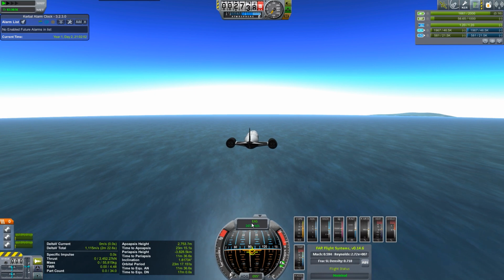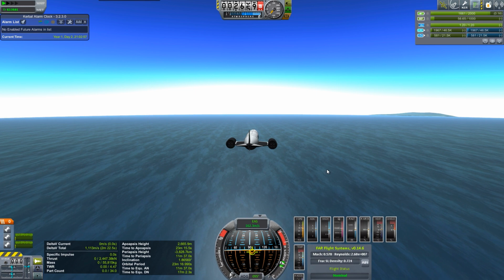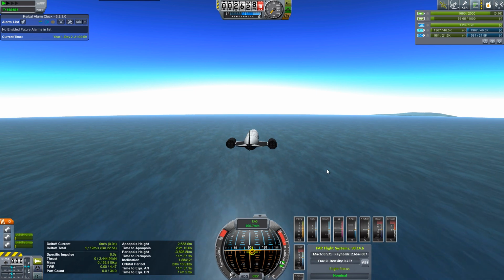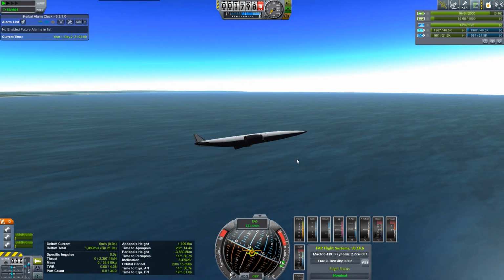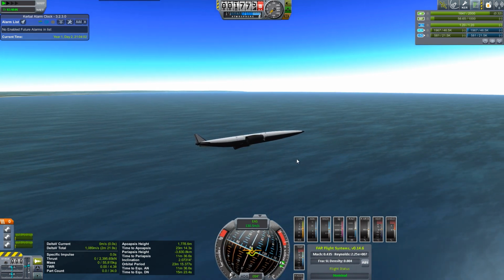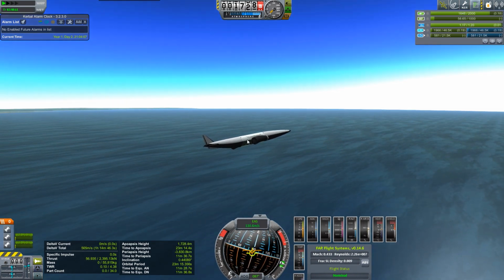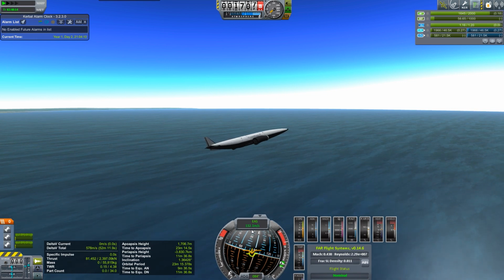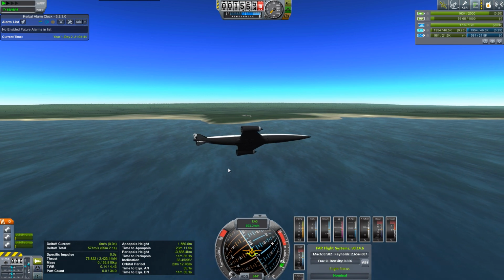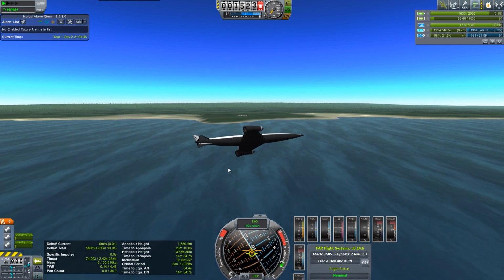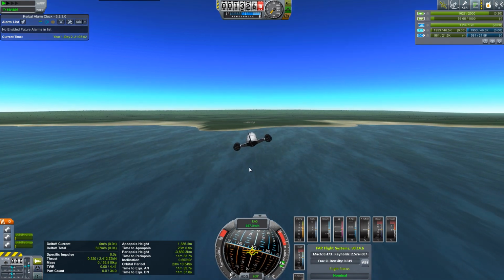Aim for an approach airspeed. We usually like it, say, about 125, and then as we descend, just before landing, we slow it down. Usually a touchdown, say, around 90. Yeah, starting to slow down a bit much at this point. Let's actually light the engines. It just needs barely any thrust. You can see already we're regaining that airspeed that we lost earlier. Okay, no, we've got this turn working just about correctly, although I am fast. All right, throttle to 0 again. Level out right about here.